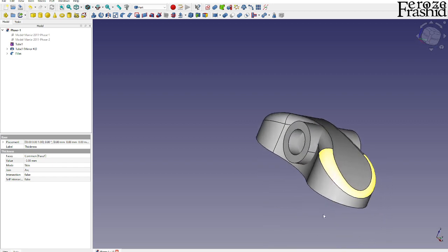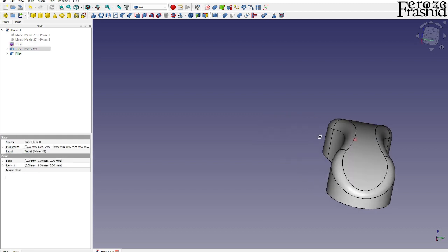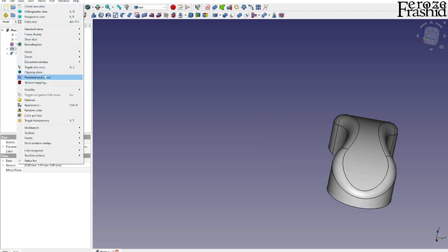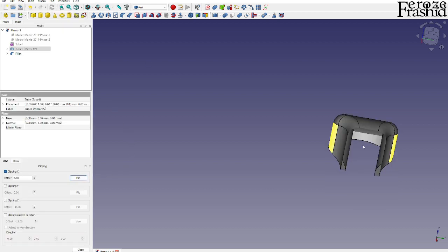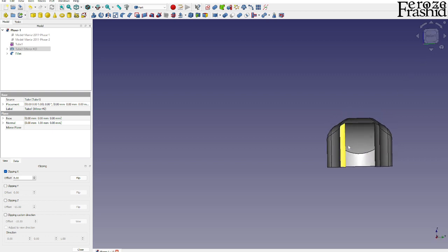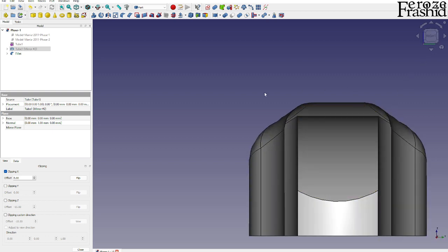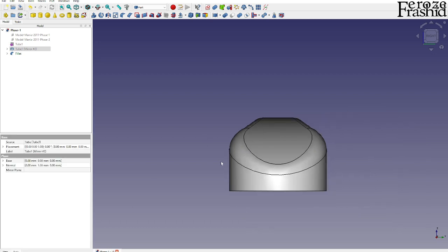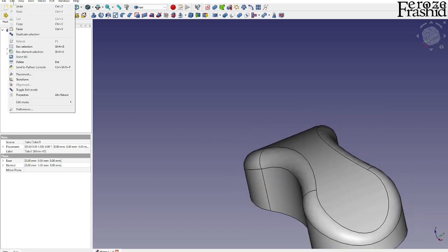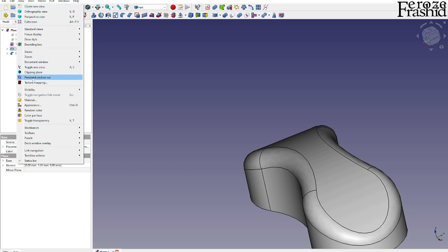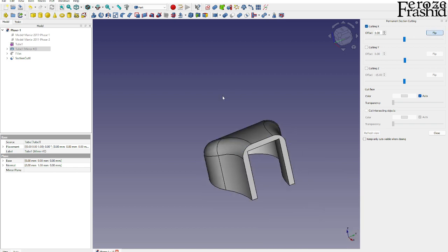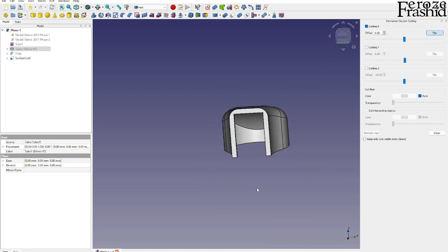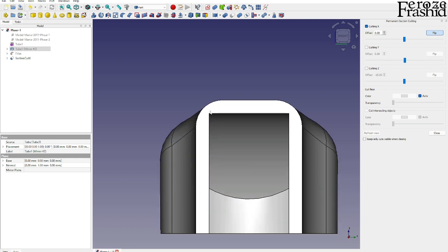What I mean by that is, let's see if we can hide these two and then view a cross-sectional view on the X side. Maybe flip the side. Now, this is not that easy to see, so we will go with view and persistent section cut, and on the X side we're going to flip the side. Okay, now it is more clear. From here you can see that at this point this is a smooth curve outside, but inside is not.